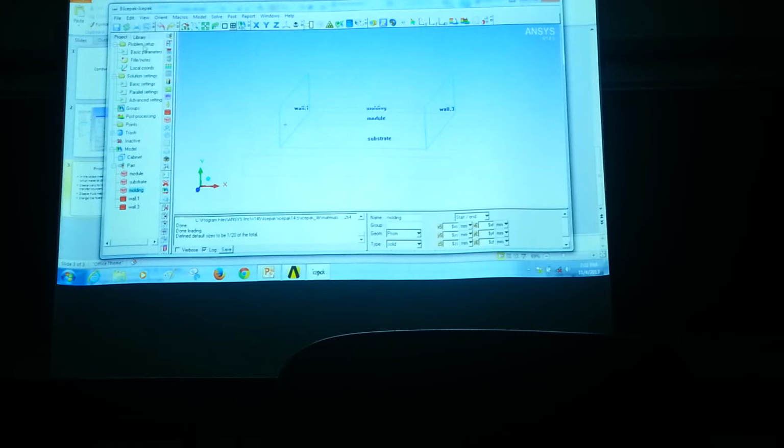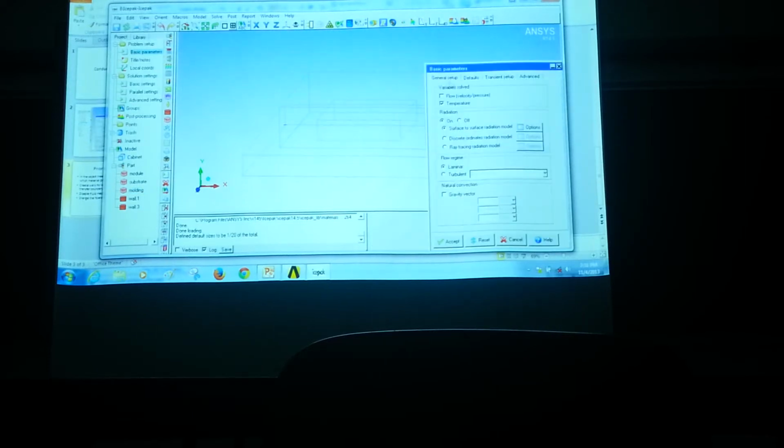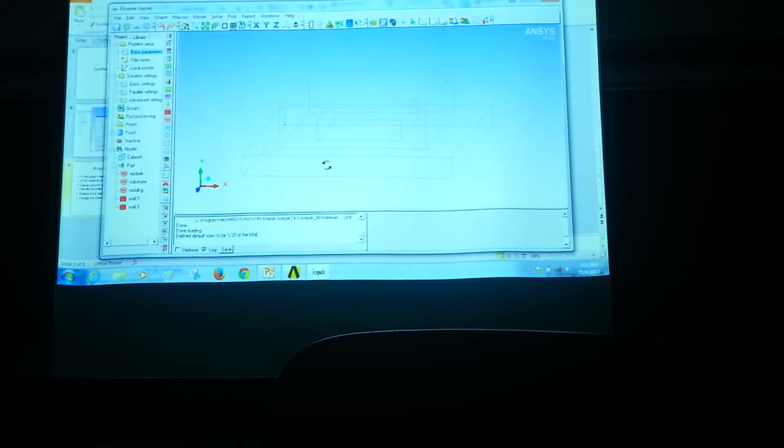Yeah, there's no fluid mechanics here. Remember, I disabled it. You went in there and changed everything to make sure it was just the basic conduction parameter, no flow. So this is strictly a conduction problem. We're going to get to the conjugate problem in a second. If you understand this, the rest of it is just the same. Now let's mesh this. Now we're going to run into your problem.